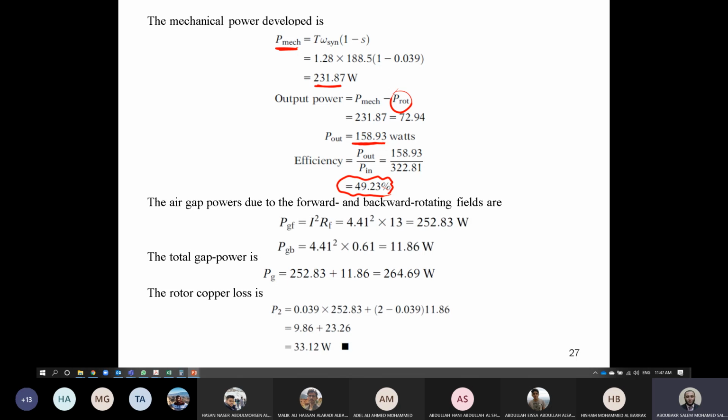Firstly, for three-phase, you have high power. And for high power, you have very small resistance, and the copper loss will be very small. So this is for high power machines. And for small power machines, you have very thin conductors, and for that, the current is small and the value of resistance is high. So the copper loss will be high.